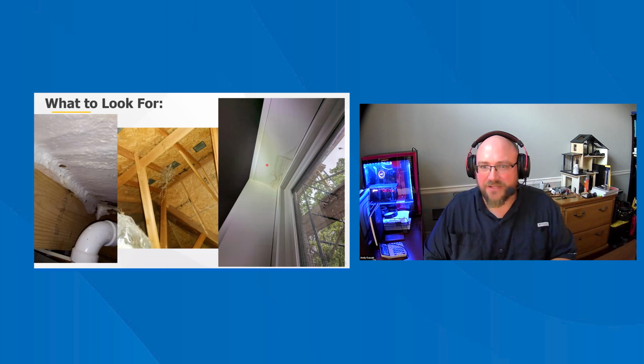And again, we had to call the contractor back out three times, and ended up putting up 3 to 4 different layers of zip tape flashing around every window, which eventually stopped the water from coming in. And then they bricked over the top of it.